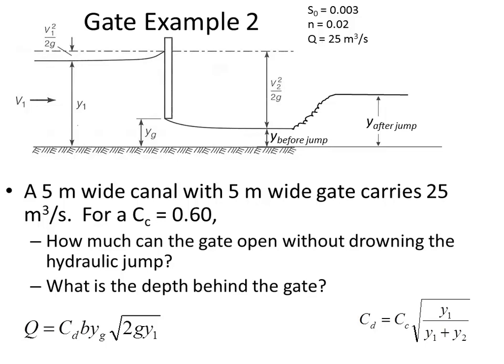And so does that mean the flow conditions are subcritical or supercritical downstream? In other words, just based on the channel slope and the roughness and the channel geometry, under steady uniform conditions, under normal flow, will we expect a subcritical or supercritical flow? How do we diagnose the flow regime when we've just got the depth? We didn't calculate Froude number. We're just using y sub c and y sub n.